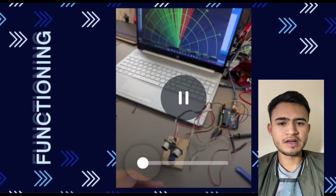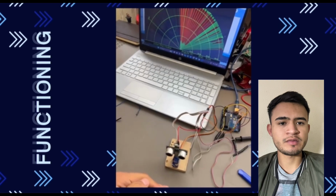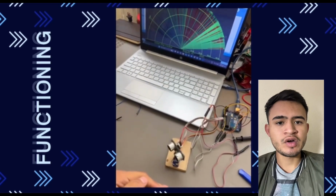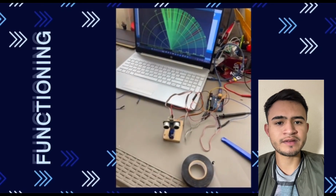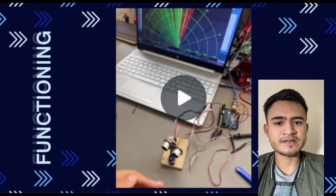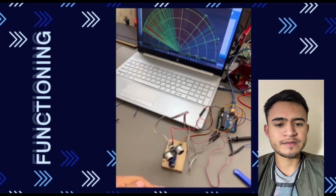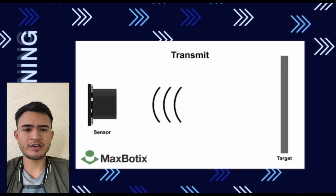The operation seems complex, but it is easier than it seems. We work with a servo motor which allows us to rotate between 0 and 180 degrees. An ultrasonic sensor is used on the servo. We use programming in Arduino for the movement of the servo and the measures of the sensor, with a program called Processing we created the graphic interface which connects to the Arduino IDE and interprets the data in a data type interface. The ultrasonic sensor works through 4 pins: voltage, ground, echo, and trigger.